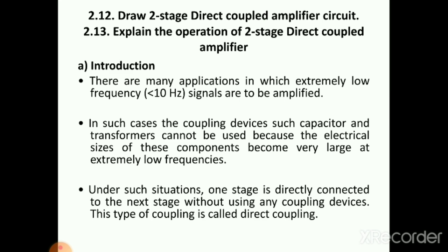So in order to avoid such bulky and expensive manufacturing of these components, we will go for direct coupling. In direct coupling, we use simple wire connections instead of capacitors and transformers. Directly one stage is connected to the next stage.